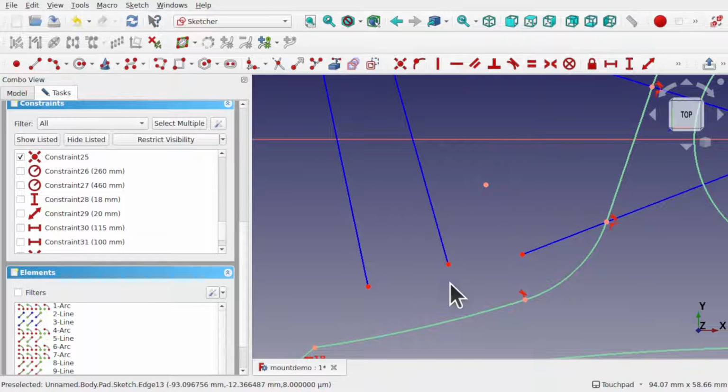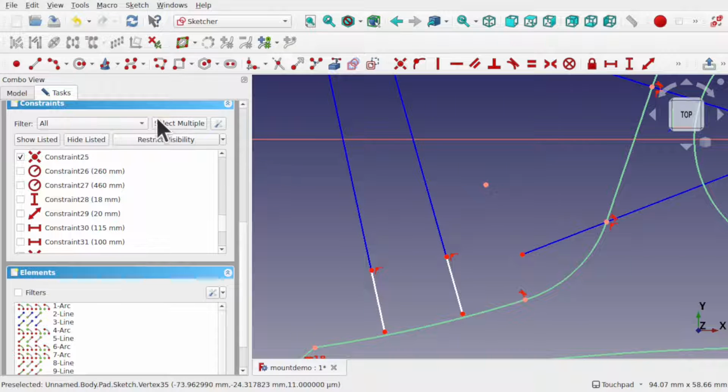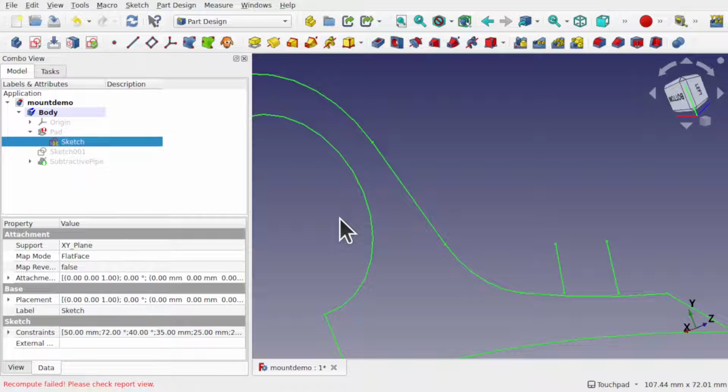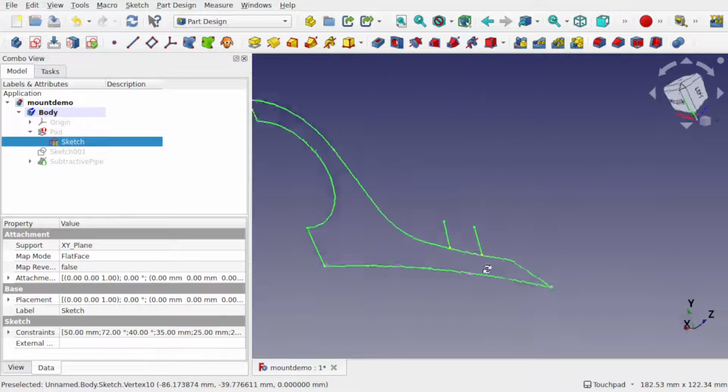So for creating construction geometry, we're going to be using lines to orientate our sketch for the holes. So I'm going to create another line now, and I can connect it coincident to this point and attach it to the line. The same on this side, coincident and point on line constraint. The reason for this is because when I bring these down closer, and we'll bring the tops down, we can add some length to this. If I come out the sketch now, hit close, we don't get a massive line going all the way up here. We just get these two little lines that sit like so.